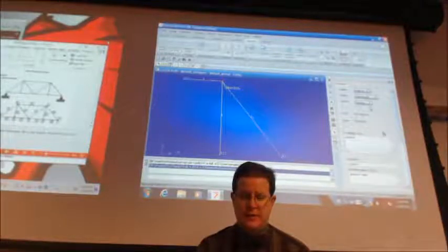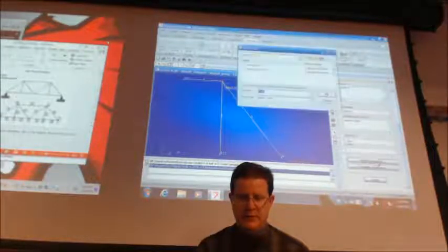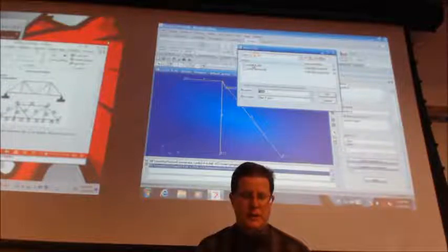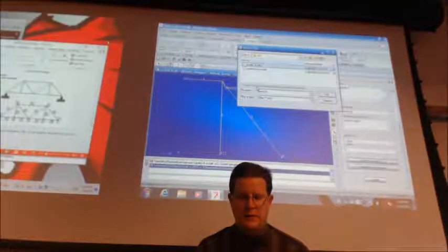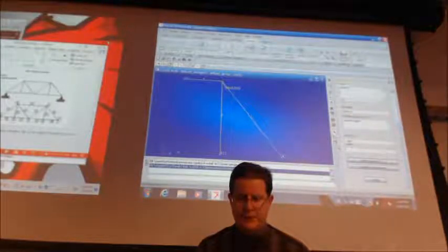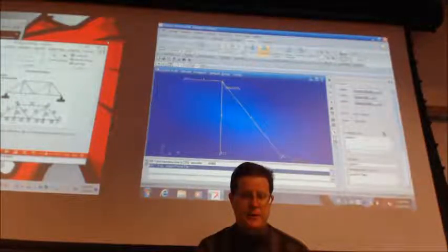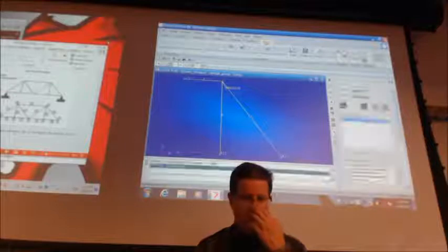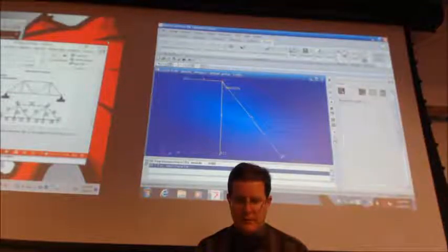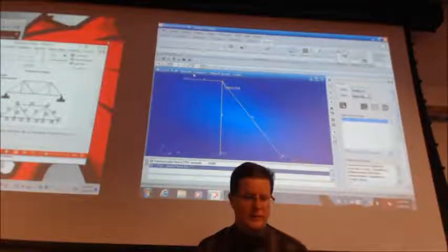So now, once it's done, you have to remember to come up here and pick XDB and select your results file. I didn't change the name on mine, so we're going to do that one. Say OK, and then apply. And now we can go to results. We know it's working because we've got results in here.